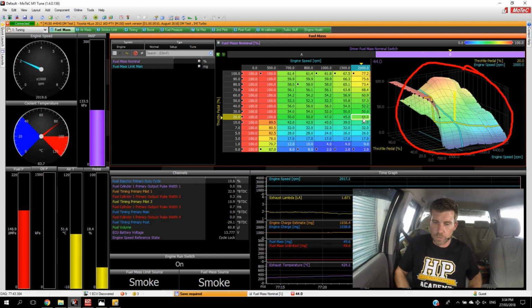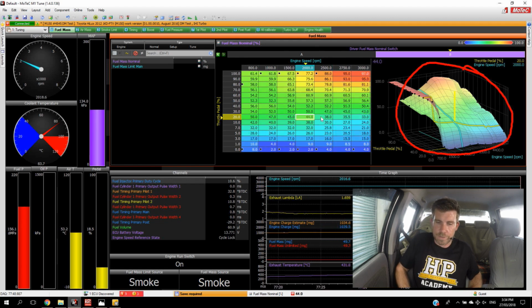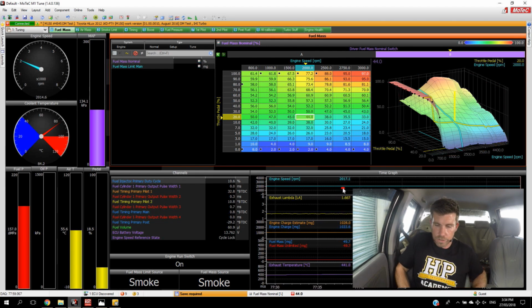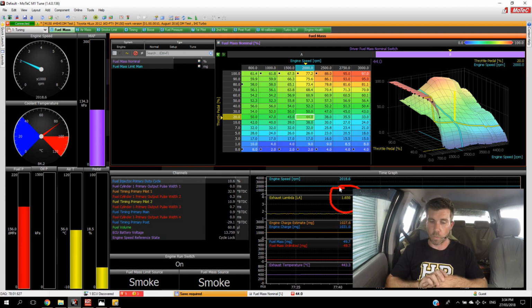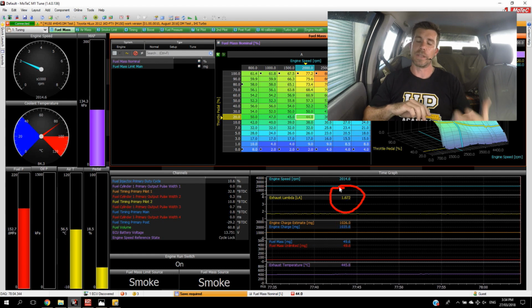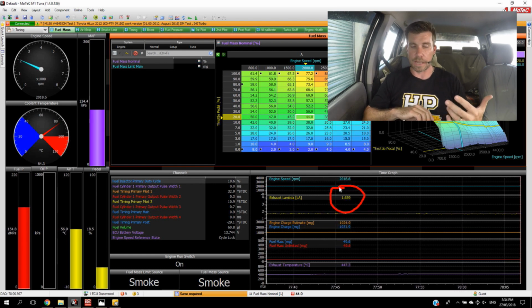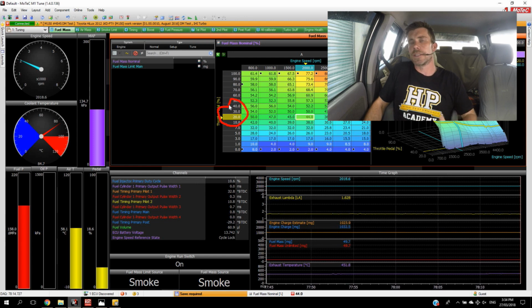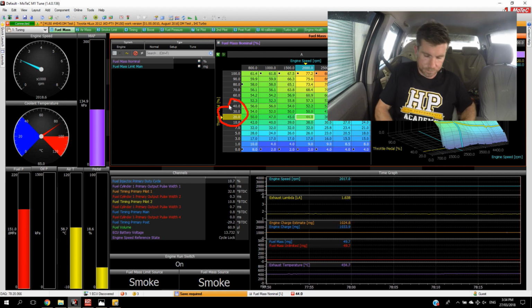Okay, so at the moment we are running at 2000 RPM, and while the relevance of this number isn't particularly important, we're basically injecting now 44% of our nominal fuel mass into the engine. Now, this also results in our exhaust lambda, which we can see at the moment being measured at about 1.65 lambda. So again, leaner than our stoichiometric air-fuel ratio of lambda 1. And we are currently sitting at a cruise throttle opening of only 20%. So this is something that we might often be running in this position when we are at cruise.